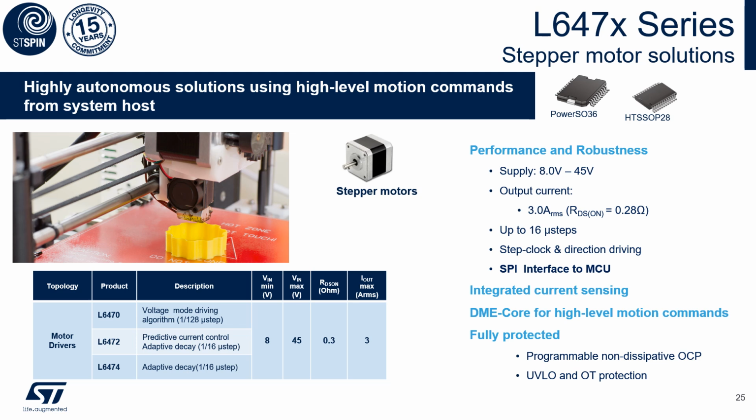They are easily programmable thanks to an SPI bus with daisy chain. They have programmable parameters and on-the-fly diagnostics. With one microcontroller, you can drive multiple drivers of this kind. They have step clock and direction driving, and integrated current sensing, which reduces the power dissipation and the PCB BOM. They also have a digital motion engine for high-level motion commands, programmable speed and positioning.